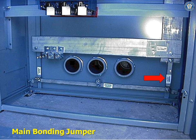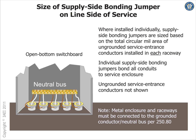It's a copper bar. If it's a copper aluminum bar like this, it's sized by UL, so we don't have to worry about it. The manufacturer will size it for you. Anything of 2000 amp or 1000 amp is typically done by the manufacturer. You can take it out if you don't want to bond them, if it's a sub panel. This is a supply side bonding jumper.